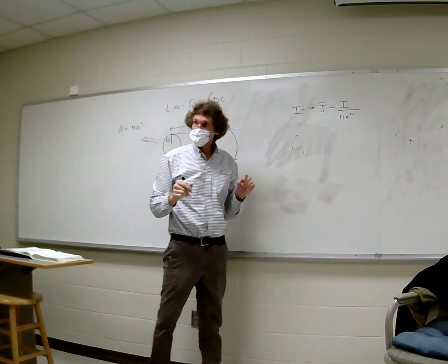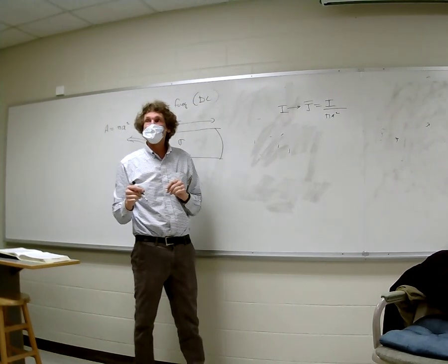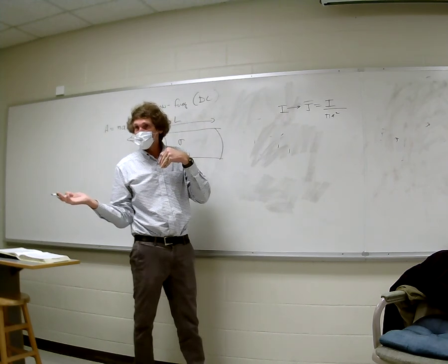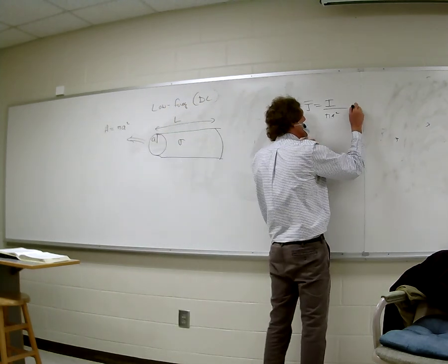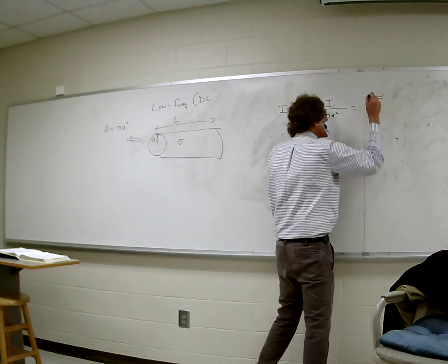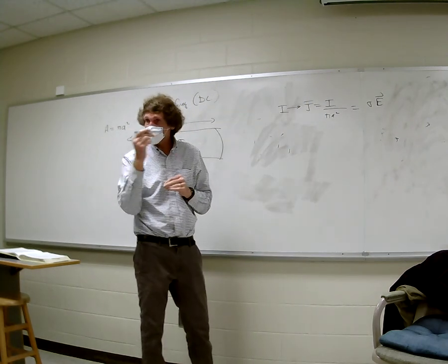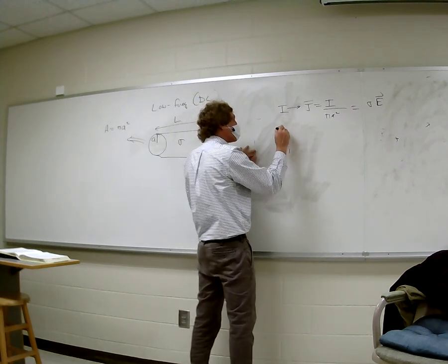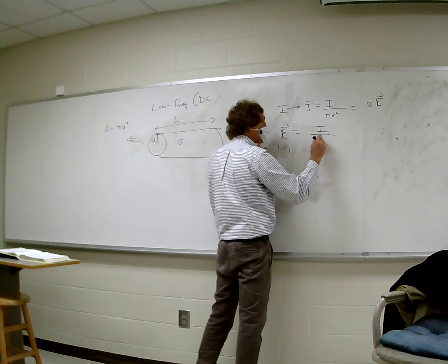Y'all remember that? Remember what happens after J? We're trying to get the resistance. I assume current, I need to calculate voltage, right? What's my next step? Get E, right? If that's J, the current density, we know J equals sigma E, where E is the electric field, is it? Correct, class? That would be along the axis of the wire if current's going in normally. And we could say that E itself here was equal to I over pi A squared sigma, right?